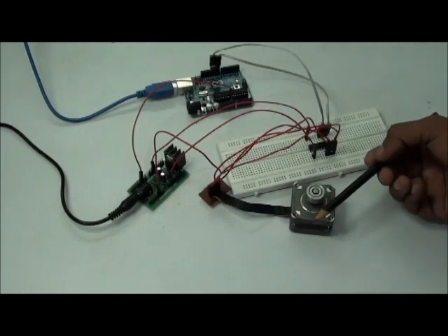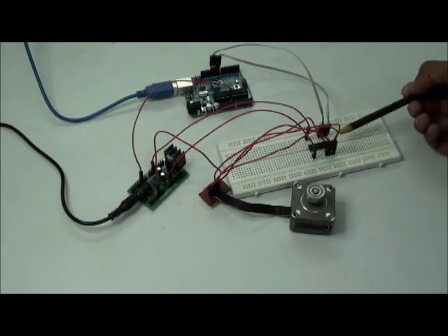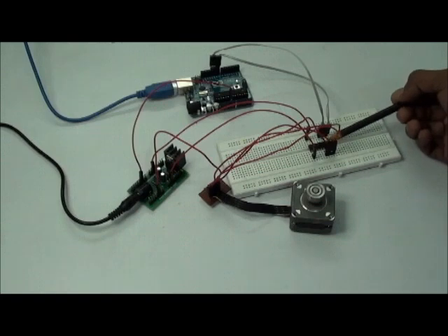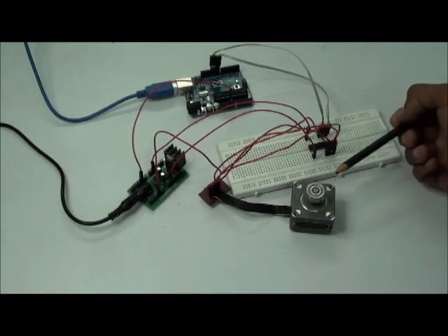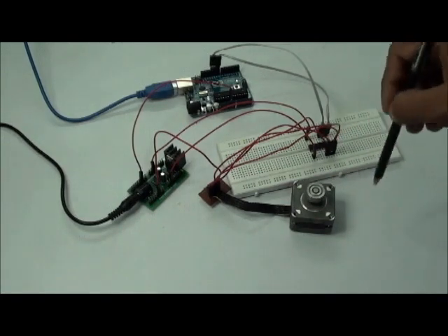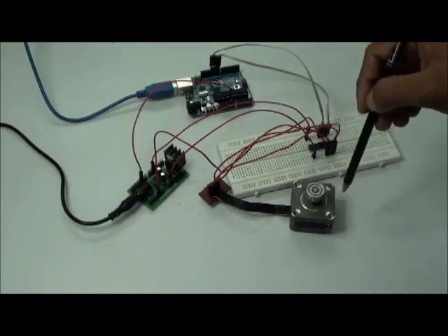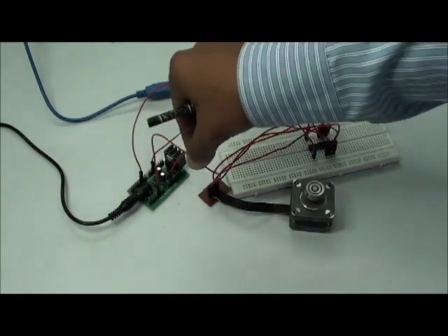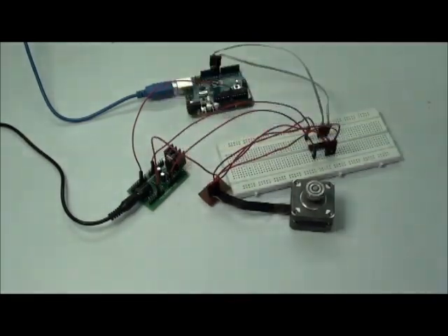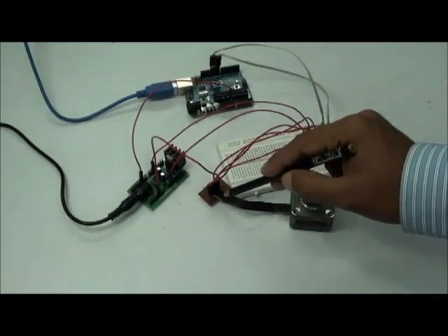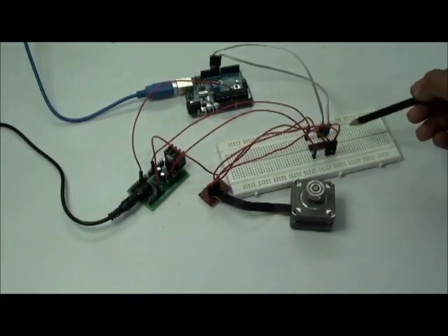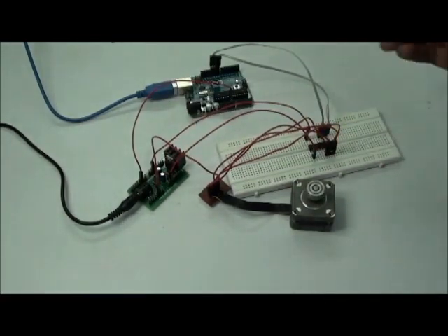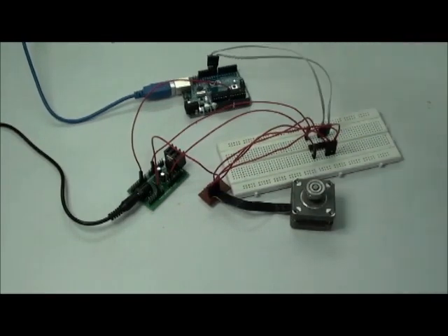This is a unipolar stepper motor. Since this ULN2803 is an open collector type, we cannot use it to drive a bipolar stepper motor. Here I am making use of a unipolar stepper motor. It normally has 4 output pins and 1 supply pin which has to be given 12 volts. These stepper motor data pins are connected to the ULN2803 output pins, and I am providing input from the Arduino.